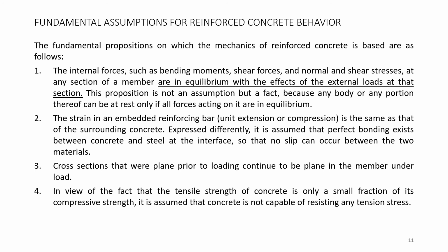The strain in an embedded reinforcing bar is the same as that of the surrounding concrete. It happens due to the bonding between these two. And in the cross section, prior to loading and after loading, the cross section remains plane.